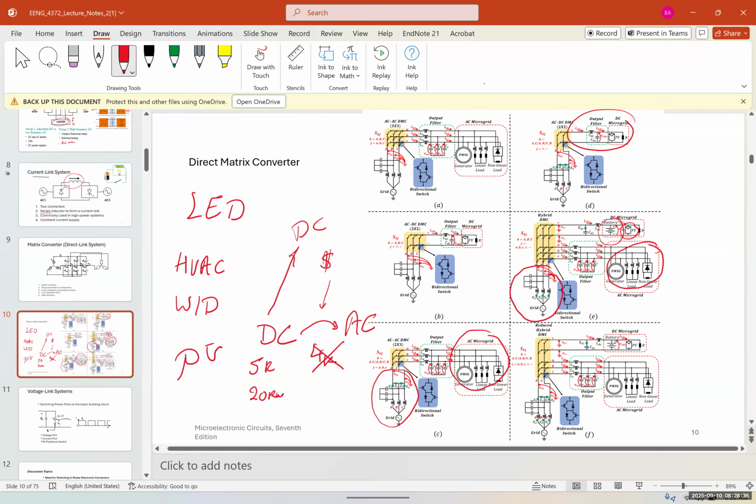But you have to be a little careful with the DC when you run them because the direction of the positive, negative, it's not like AC where you can plug into your outlet any way. So sometimes there are special outlets for those. But if you want to just run your lights, all the lights that you see in these rooms, LEDs, they usually run on 5 or 12 volts. So you can run an entire RV with a 12-volt system or a 24-volt system.